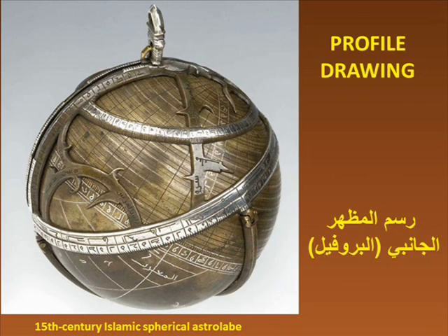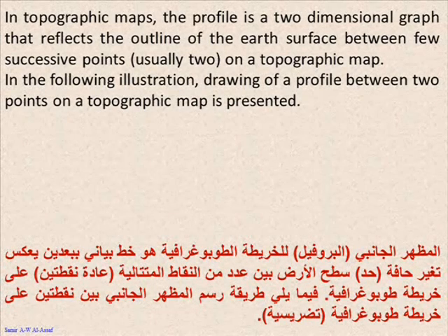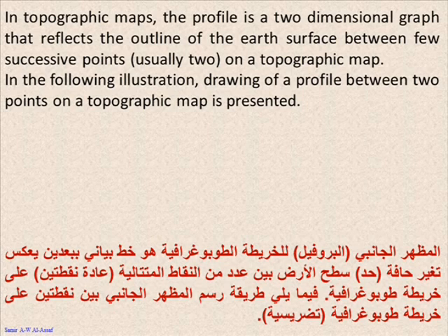Profile drawing. In topographic maps, the profile is a two-dimensional graph that reflects the outline of the Earth's surface between few successive points on a topographic map. In the following illustration, drawing of a profile between 2 points on a topographic map is presented.